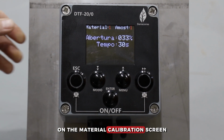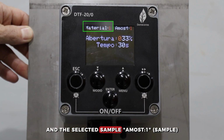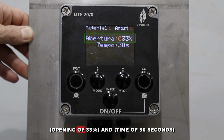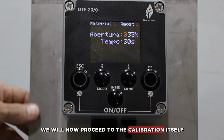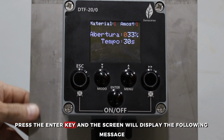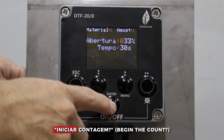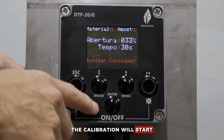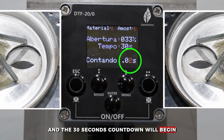On the material calibration screen, the selected material, Material 1, and the selected sample, Amostra 1, are displayed, in addition to the default information, Abertura de 33% and Tempo de 30 segundos. Once the appropriate settings have been made, we will now proceed to the calibration itself. Press the Enter key, and the screen will display the following message: Iniciar contagem. Pressing Enter another time, the calibration will start, and the product outlet gates will open to 33%, and the 30 seconds countdown will begin.